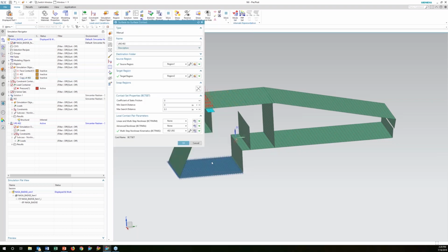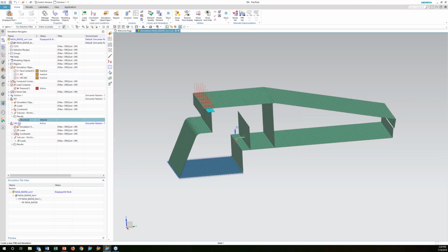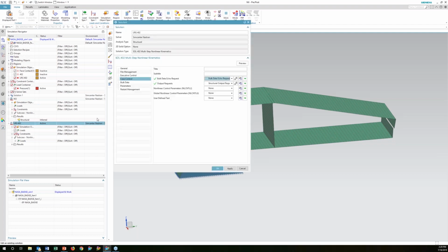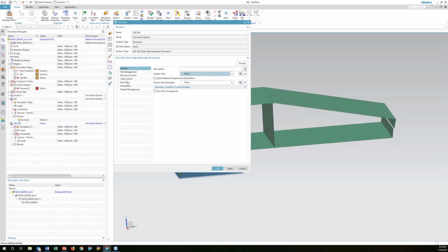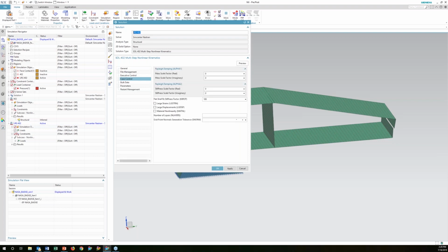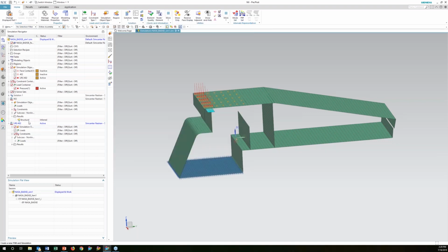And then for the solution, I would also want to toggle on large displacement parameters. There we go. So toggle on large displacements here if I want to include those large displacements in this analysis. Now, I'd go ahead and solve this, but it took me 25 minutes to solve. So we'll just do this little trick and pull it out of the oven here, completed.